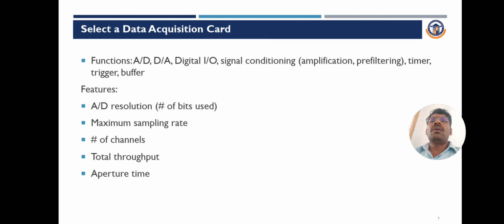So this is true of most cases, but it is not true for all cases. In many cases, the physical quantity is directly converted into an electrical quantity by a transducer. The first stage of a measurement system is known as the detector-transducer stage, a variable conversion element. The output of the primary sensing element may be an electrical signal such as voltage, frequency or some other electrical parameter. Sometimes this output is not suited for the system.